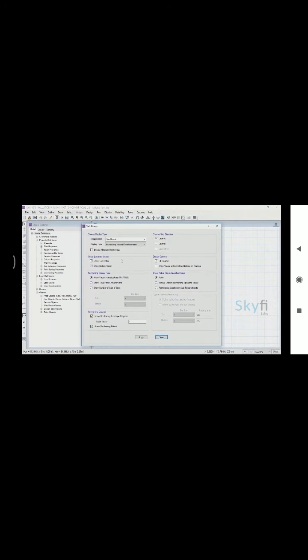Next, go to Display, and click on Show Slab Design. The Slab Design dialog box appears, where you will have to choose the required options. Select the Design Basis option, as strip-based. You need not make any other changes for now. Click on Apply. Click on Close, to remove the box. Now the reinforcement intensity, for both top and bottom bars of the footing is displayed. This intensity value is given in millimeter square per meter, that is area of steel in millimeter square, per 1 meter length.